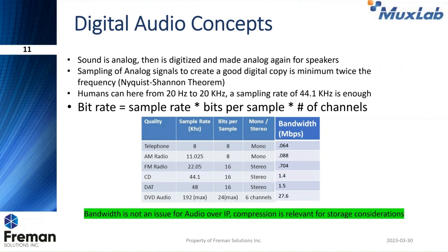Do we have to worry about audio? Very quickly, the answer is no. Audio, even at the sample rate of DVD quality, 192 kilohertz, which is more than required by Shannon and Nyquist, at 24 bits per sample, which is a ridiculous amount of detail on the information of the signal, and nowadays we can even go to 32 bits, even 5.1 channels of audio, the signal only gets to about 27 megabits of bandwidth, which is really nothing compared to the capability of a network to carry bandwidth.